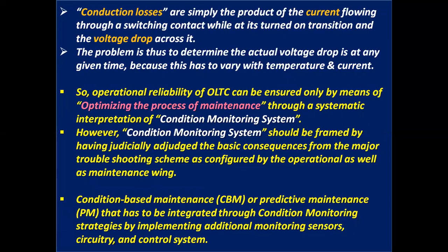Conduction losses are simply the product of the current flowing through the switching contact while at its turned-on transition and the voltage drop across it. The problem is thus to determine the actual voltage drop at any given time, because this varies with temperature and current.